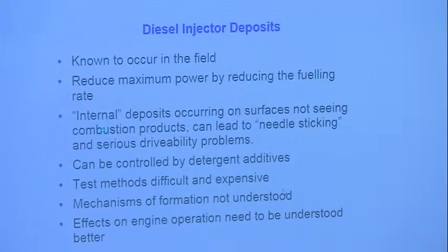Not internal deposit, but the deposit plugging can be controlled by detergent additives. Once again, the test methods, as I just mentioned, are very difficult and expensive. And I think after about 5 tests, the entire engine has to be changed because it can't stand that kind of operation. Mechanism of formation is not understood, especially for internal deposits. And effects of engine operation need to be understood better, especially on internal deposits, okay?